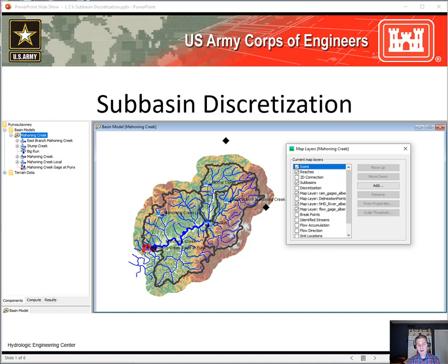You have the Mod-Clark method, which uses excess for each of those grid cells that you define, and then routes that excess precipitation to the subbasin outlet. Not from cell to cell, but from that cell to the outlet using a very simple linear reservoir. The other option is the 2D surface flow option. So if you do want to use 2D surface flow, then you can choose an unstructured discretization method in HMS and then apply that gridded precipitation to the mesh, or the unstructured mesh.